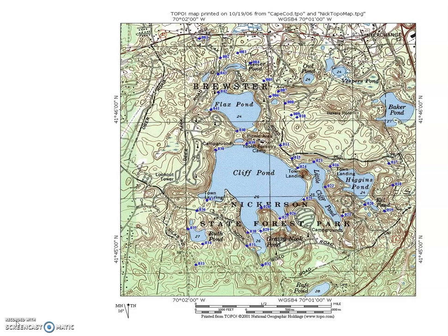So in your lab manual on page 35, just under that data table, there are some instructions for you saying using Table 1's data, which is the table you just looked at on the other page, plot the recharge area of a well on Lookout Tower on the map if it is pumped at a rate of 0.8 million gallons per day.